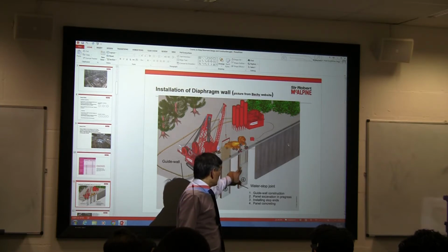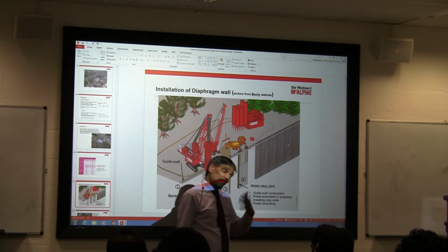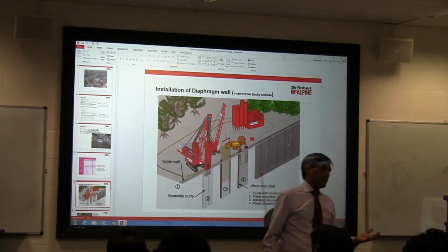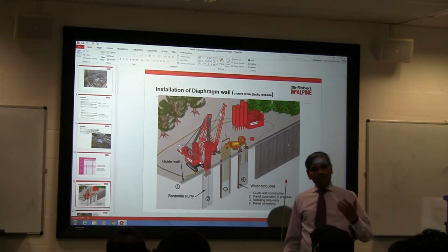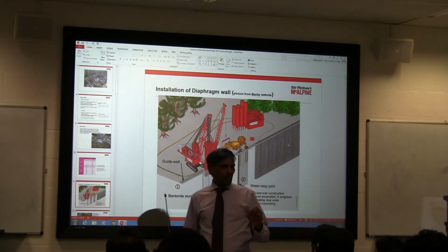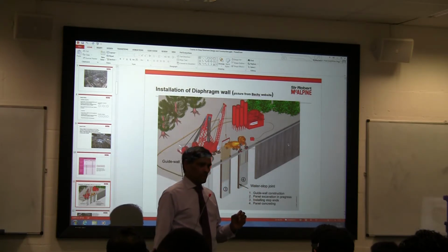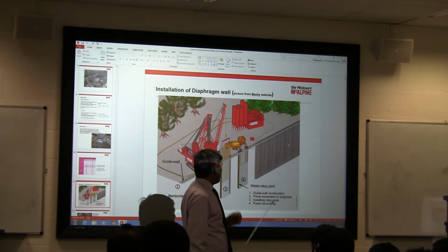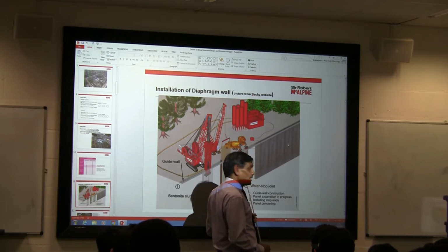Because this wall, we are going to pour 70 meters. And again, you have to think about what is the volume of concrete that is going. Because in London, there is a restriction. You can't do 24-hour operation. Some of the times, we may have to go for a special permission to get 36 and 48 hours of